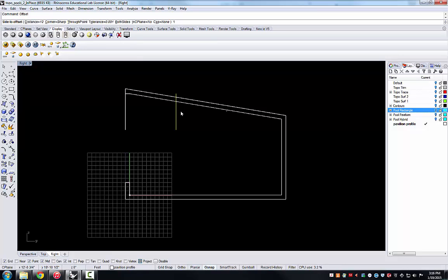In this case, I'll put 1 because we're working in feet, not 12. 12, again, would get you 12 feet. The number 1 gets you 1 foot. And if you wanted to say 6 inches or 8 inches, you would type in 6 and the inches.